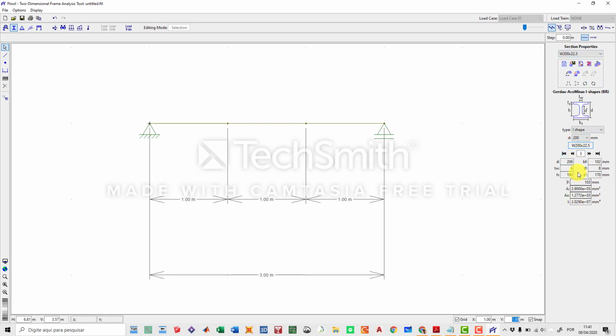that section properties. Here we have the length, the total height of my section, the web thickness, the flange width, the flange thickness, right? It also calculates the geometric center, the area, and the inertia. You also can rotate, if you like, your shape. And then when you rotate, it's going to calculate the smaller inertia, okay? And after that, I select my frame, and then I click Apply to All. All right, so I finished applying.